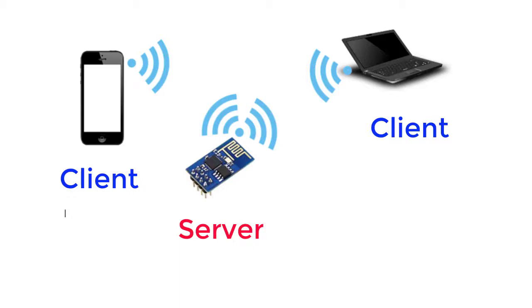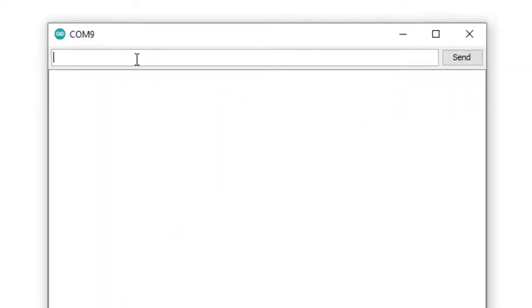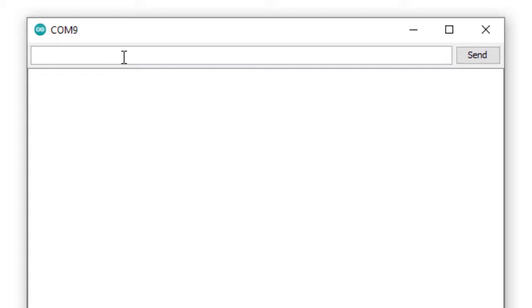Now I am going to show ESP8266 as a server, with my mobile or PC as the client. Both are in the same network. In my case, the Wi-Fi network is generated by my mobile hotspot. I need to connect my ESP module with the access point, so I am checking the present access points sensed by ESP. The command is AT+CWLAP, which lists all access points.